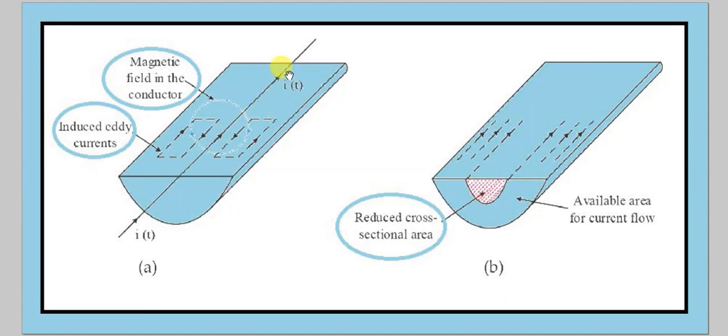or reactance inside the material. So what happens in this conductor is that with the higher frequency, the area of cross section for the flow of the charge is reduced. Here we can see that the current is pushed towards the surface of this cylindrical conductor. We have taken a cross-sectional slice through the radial part. We have cut it into two pieces. Here the current is flowing closer to the walls or the surface, while the inner region is being vacated due to the very strong agitation of the induced eddy currents. So the available area is now this. That is the phenomenon we call skin effect.